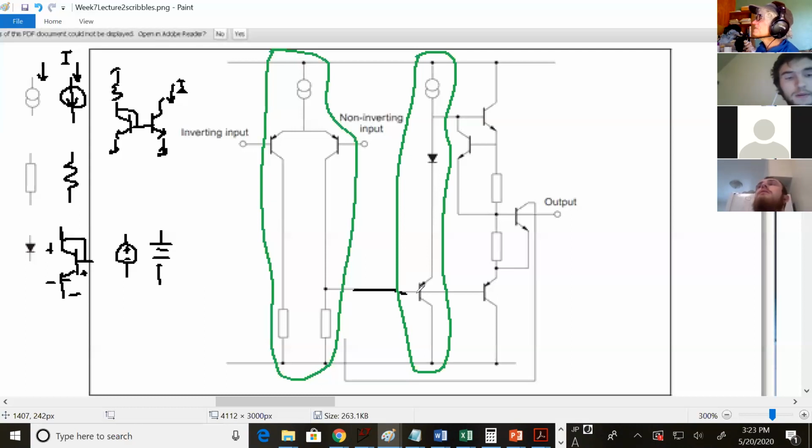There are 2 reasons. Is one of the reasons that it's acting as a buffer? Okay, and what are the characteristics of a buffer? They don't draw current, and they supply a lot of current. Exactly. So maybe they took this diff pair and connected it up to the next circuitry, and it stopped giving as much gain as it did before. Something happened. So yes, this could be protecting the diff pair from the next circuitry.